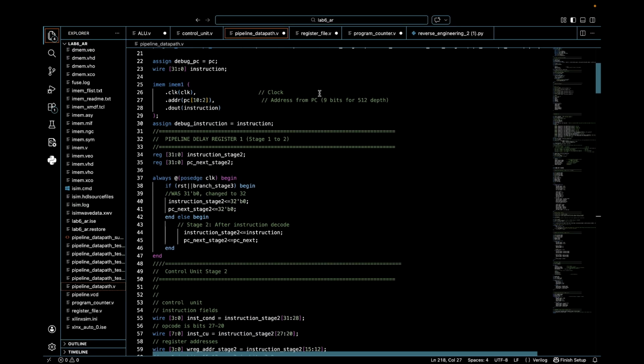Just like the last lab, for both the IMEM instruction memory and the data memory, we used the IP core generator, in particular project, new sources, IP core generator. For the instruction memory, we chose a single port ROM, and for the data memory, it was a dual port RAM. Because each instruction is 32-bit wide, the width is 32 bits, and the depth is 256 8-bit address. For the data memory, the width is 64 bits and the depth is 512.